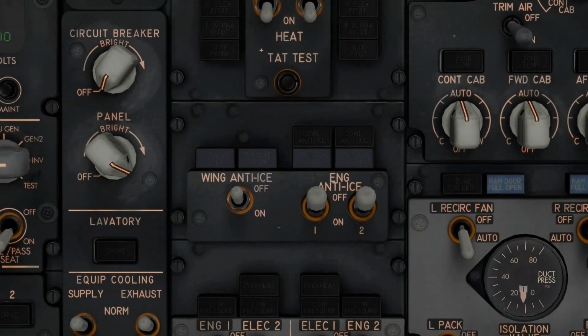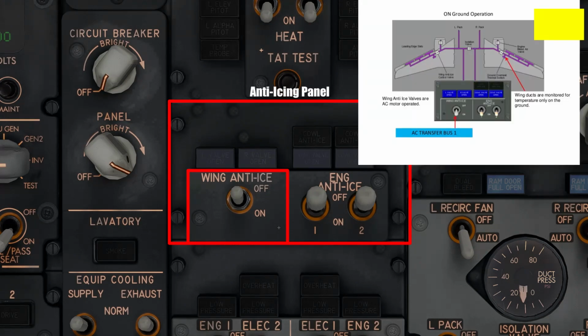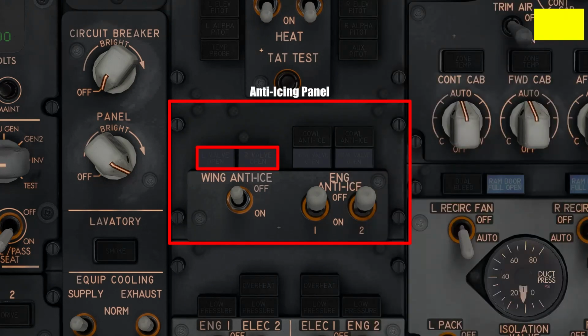Alright, moving underneath these switches is the anti-icing panel, where on the left side we have the wing anti-ice switch. Now, just like the APU, the engines also produce hot bleed air which can be introduced into the wing through the leading edge slats of the wings in order to prevent buildup of ice and maintain safe operation of the aircraft even in cold conditions. The light above illuminates brightly when the valve allowing the bleed air in is opening and becomes dim when it is locked open in a stable position.